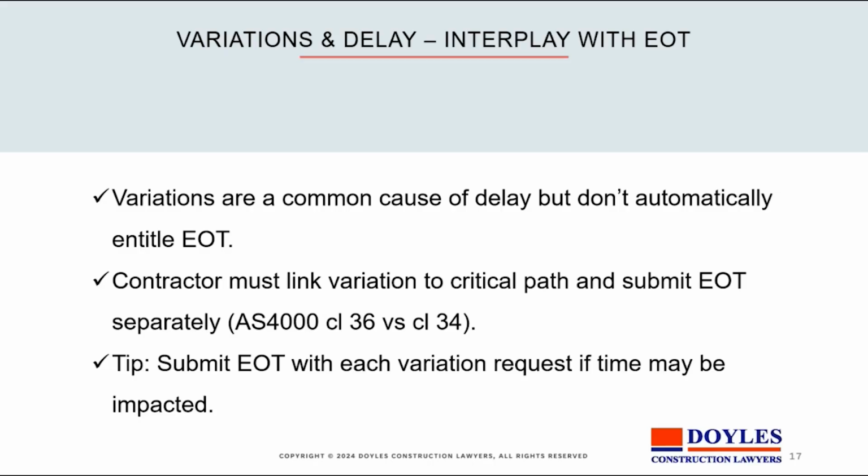The other aspect that should be looked at is variations and delay and their interplay with extension of time claims. Variations, which stands for any claim you can't give a better name to, together with any change in the work or the method of work or the sequence of work, they often don't involve an EOT. If, for instance, you're varying the colour of the front door, then that's probably not going to get any extension of time, provided it was notified some distance out from the door's installation. On the other hand, some EOTs cause a major interruption to the construction.